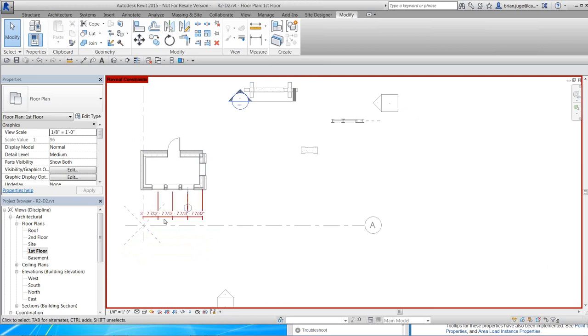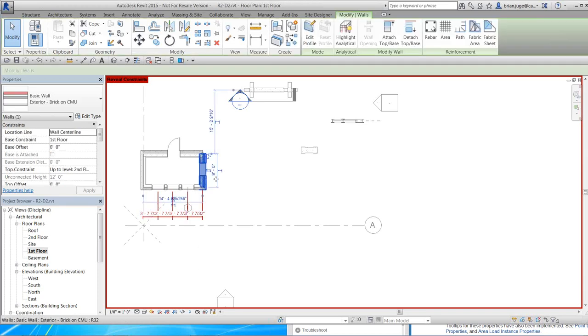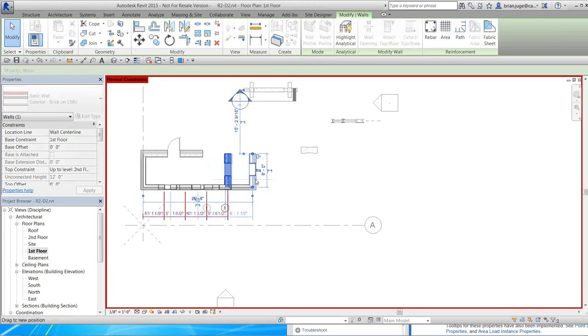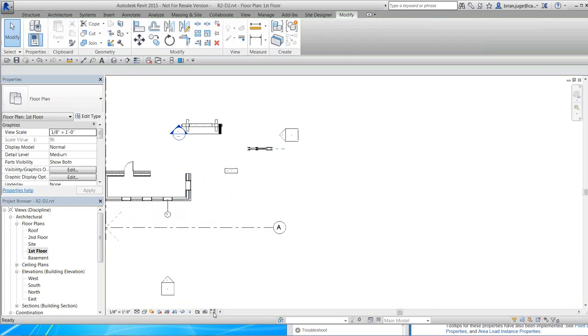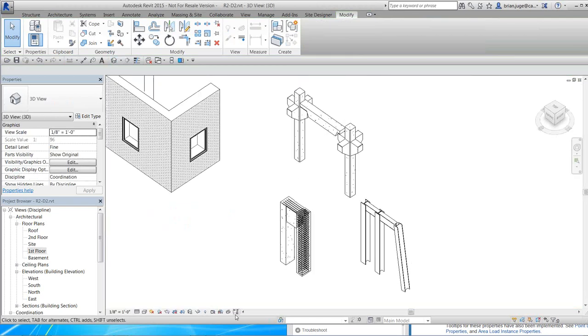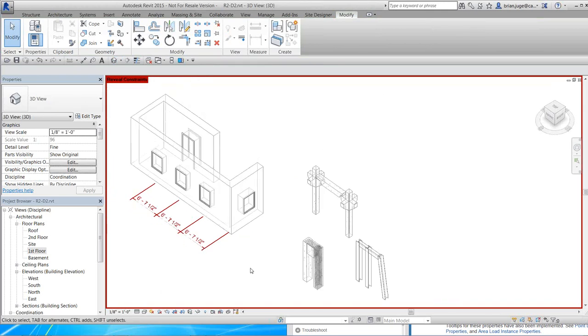Now these are equals constraints. It doesn't display the text equal, but it at least turns on and says, hey, you have an equals constraint in here that's working in that view, and I can go and track that down. So if you've got weird behavior happening within your walls, your joints or something, we can go in here and turn that on. That's just a newer feature to have, that we can go in and track that down. And the beautiful part, again, is this will show up even in 3D views, showing and displaying that particular thing is equal to constraint, and that rule set, that constraint, is working within the program.